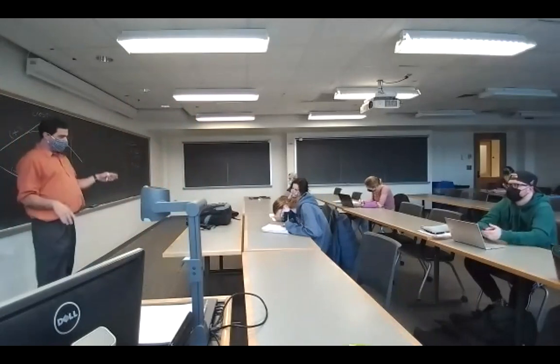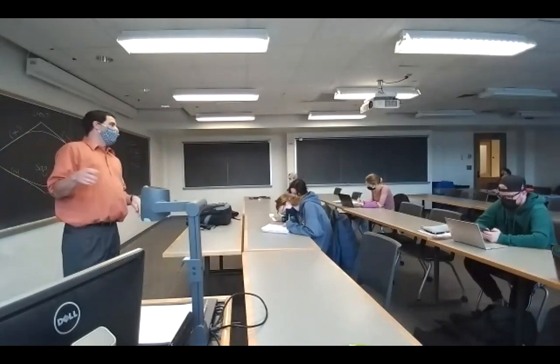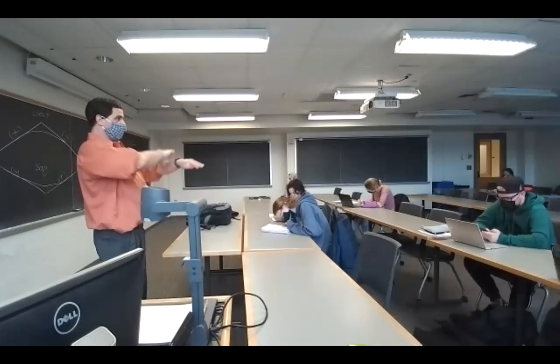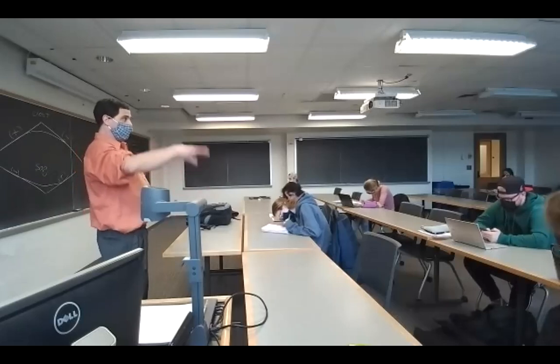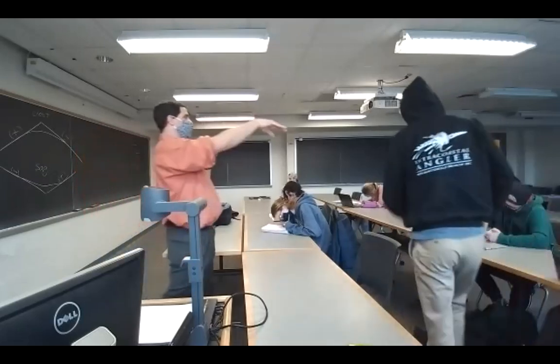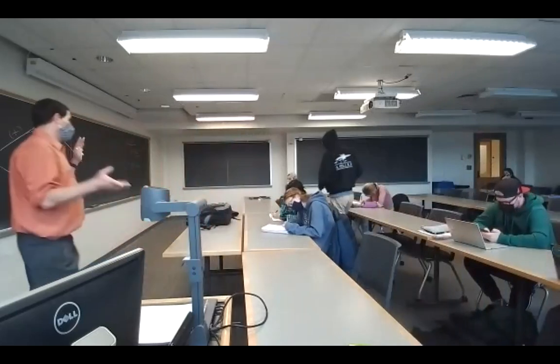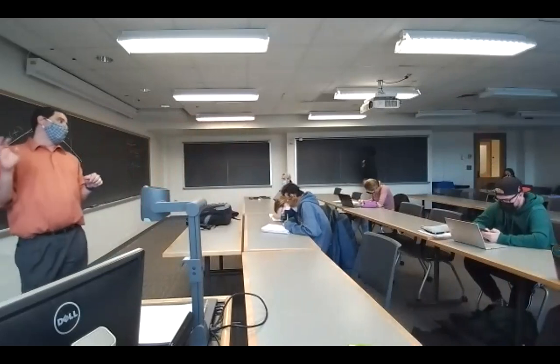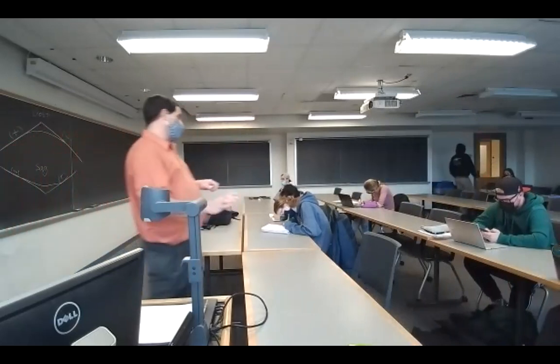So you have passing sight distance and stopping sight distance. For passing sight distance, you're assuming that the object is 3.5 feet high also, because you're passing each other. 3.5 feet. Stopping sight distance, the object height is half a foot.